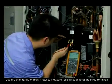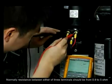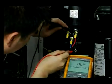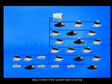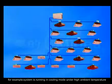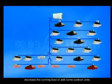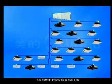Use the ohm range of the multimeter to measure resistance among the 3 terminals. Normally, the resistance between any two of the 3 terminals should be 0.9 to 5 ohm, and the resistance between terminals and ground should be infinite. If the resistance is abnormal, please change the compressor. Step 2. Check if the system load is too big. For example, the system is running in cooling mode under high ambient temperature, or overmatching of the indoor side leads to high evaporation temperature. If so, you can turn off some indoor units to decrease the running load, or add some outdoor units. If it is normal, please go to the next step.